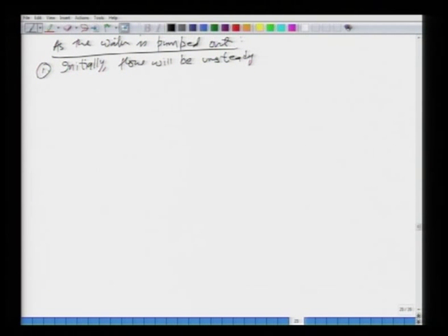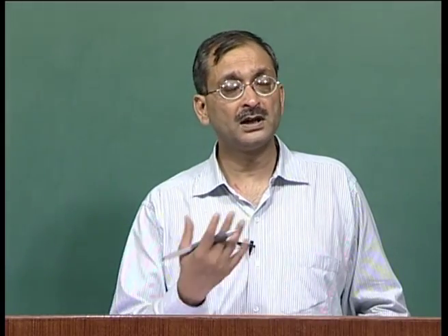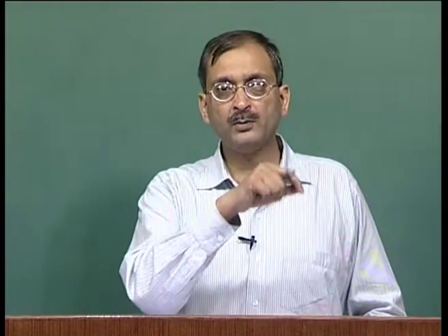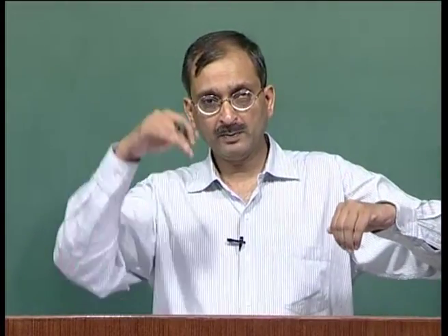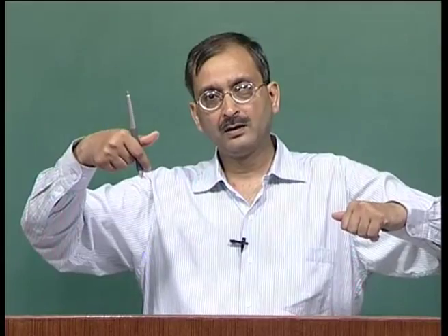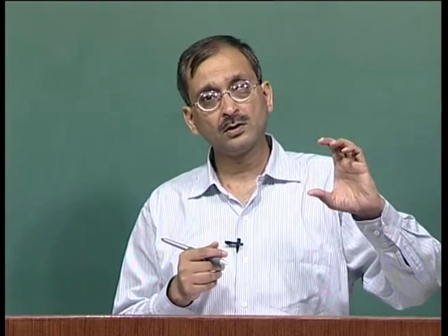That is to say, your H will be a function of what? Both R and T, and also your S will be a function of both R and T. So, during the initial phases of the pumping, the flow is unsteady. That is to say, if you take any radial distance R, for example, you have a pumping well and then you have an observation well at a distance of R.